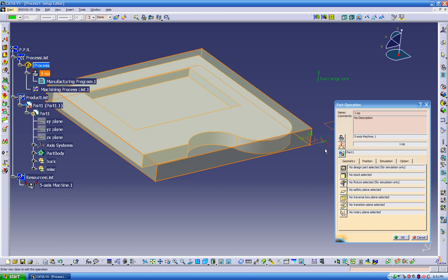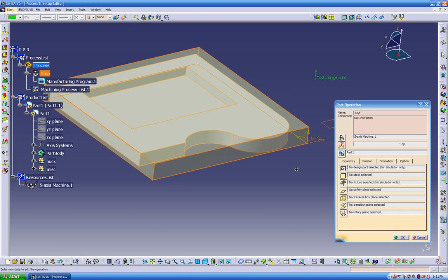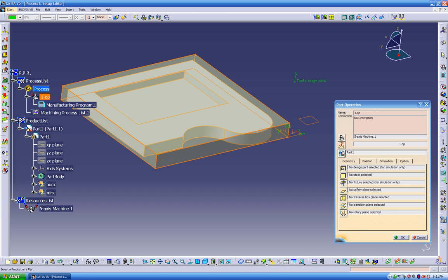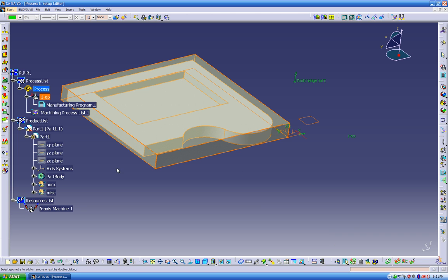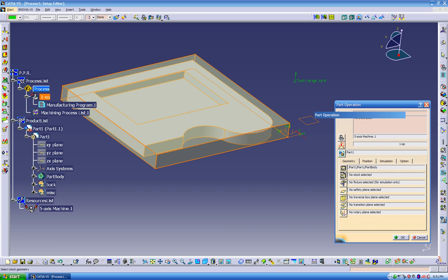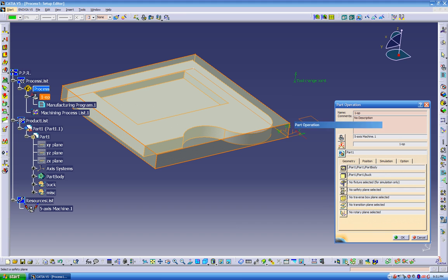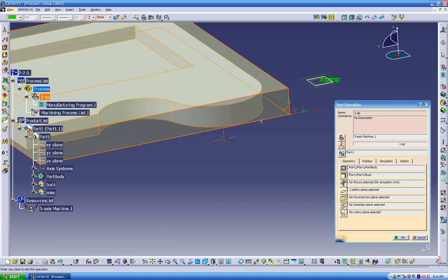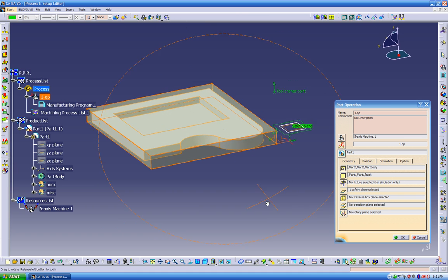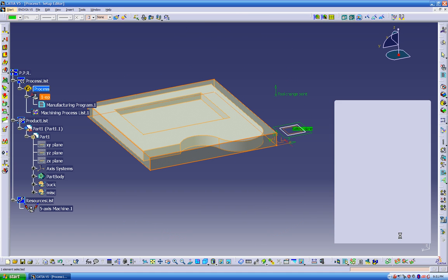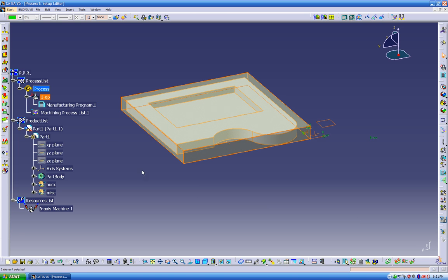And then the clearance plane is this plane right here. That's why it's very important to keep in mind: we have our axis, we have our stock, and our plane. And then it was very easy. We can click on part, double click on the screen 2 times, click on our stock, double click on the screen 2 times, click on the plane, we click on the clearance plane, you see it automatically puts a safety plane in there. Now we click OK. So we set up our machine.